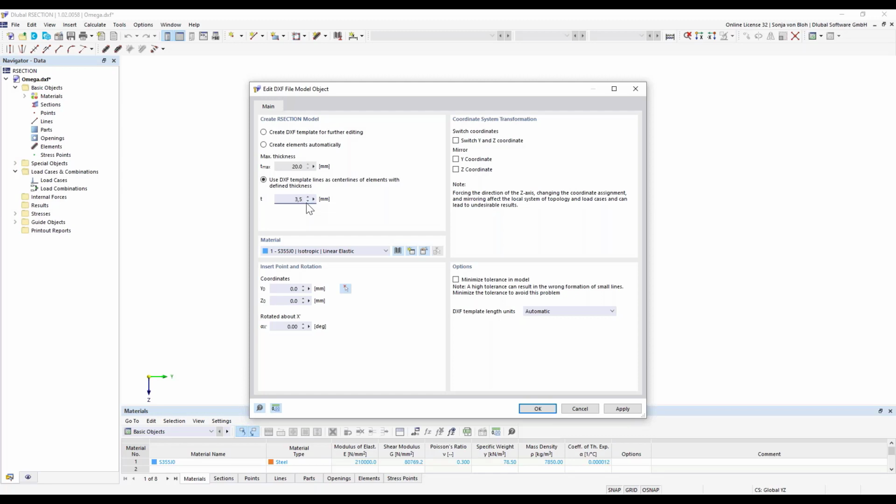Elements are required for the calculation using the thin-wall analysis and for the calculation of the effective cross-section, since only then are the subpanels available. The subpanels are required for the classification and calculation of the effective cross-section. If no elements are defined, the cross-section is treated as a class 3 cross-section in the design add-ons.